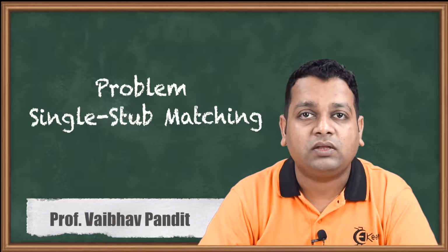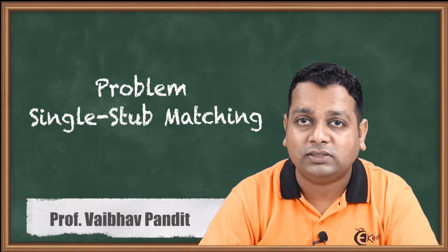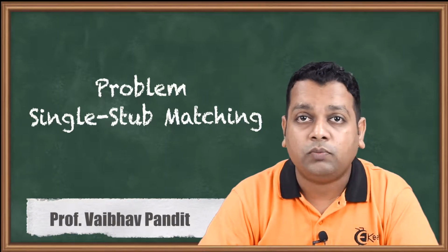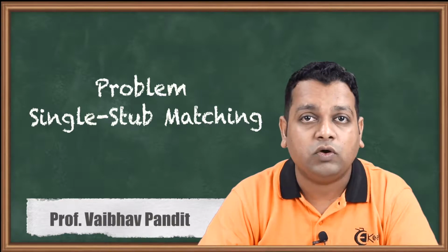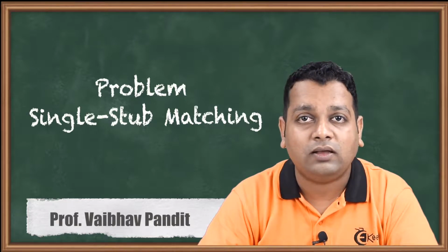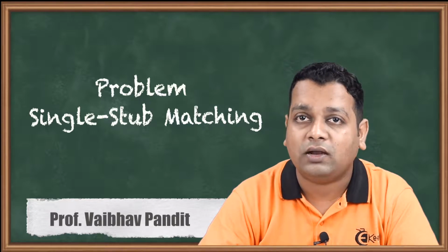We started with the help of the circuit model involving the lumped elements RLGC. We have also derived the transmission line equations for the voltage form and the current form. Now we have the knowledge of reflection coefficient, transmission coefficient, and what exactly the standing wave means. The standing wave ratio is also formulated. We have the knowledge of line impedance and line admittance also, and all this information related to the analysis of